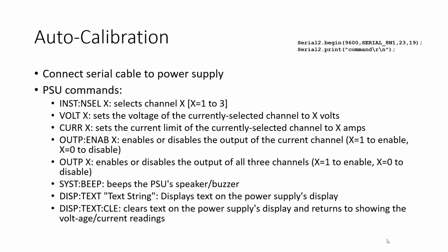Okay. So this sets up the serial and then you can just print. The only other thing you have to know about printing is that every command needs to end with \r\n, because it's using the old carriage return new line convention that Microsoft has cursed us with for the past 57 years, as opposed to just the Linux style new line, \n. You got to use \r\n.